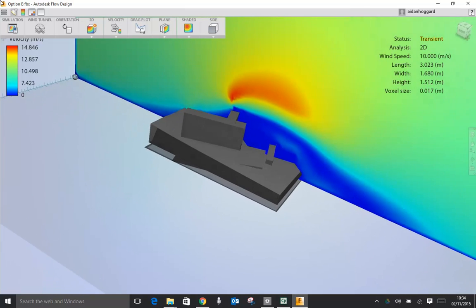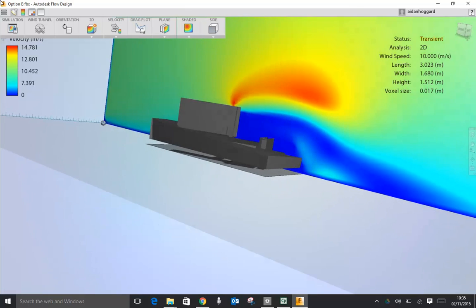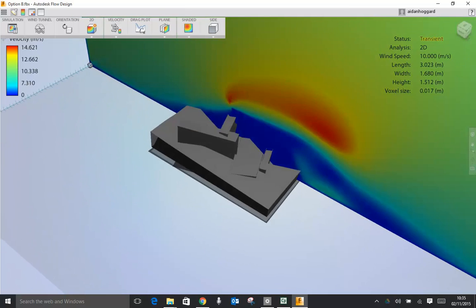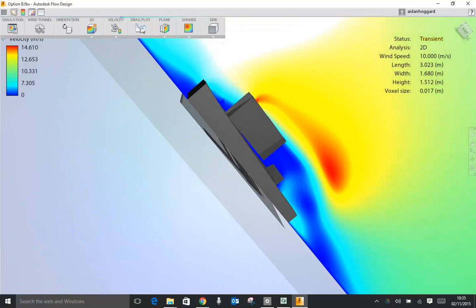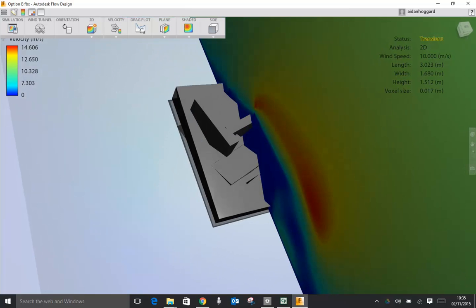Then also you've got your normal mouse controls, but slightly frustrating, it doesn't use exactly the same controls as Revit. So panning is slightly different. It's the left mouse. And also, the reason I don't use my mouse in Flow Design, what tends to happen, you end up with your model on its side because it does not constrain it to a vertical axis, which is quite frustrating.